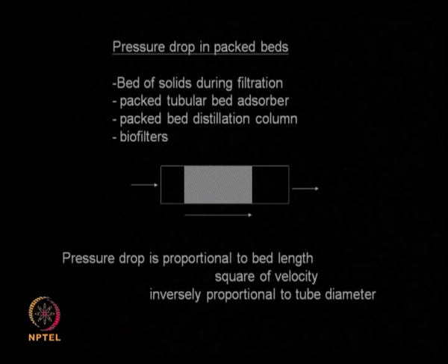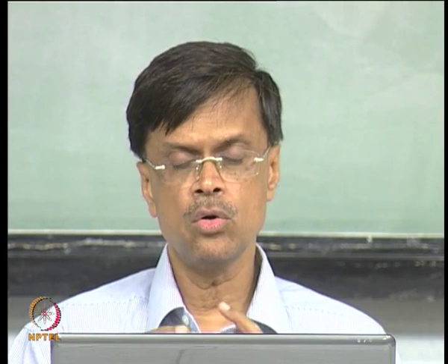Now you also have to consider pressure drops, because when you have a packed bed and when a solution flows through it, whether it is a gas or a liquid, the fluid can flow only through the interstices, the packing material offers resistance, and so there is always a pressure drop. So the feed that is entering the packed bed has to overcome this particular pressure. Either it is achieved by having pumps, so that the pump can deliver enough pressure for the fluid to pass through it and come out through the other side, especially if the packing is very long, or if you have very small particles, then pressure drop will be very high.